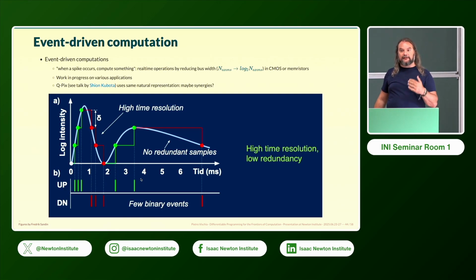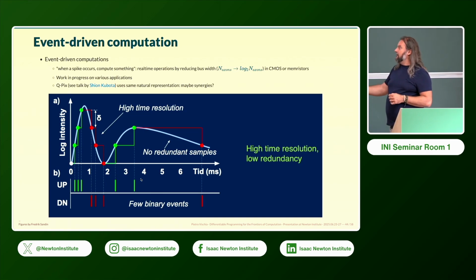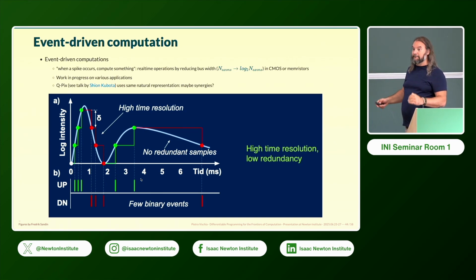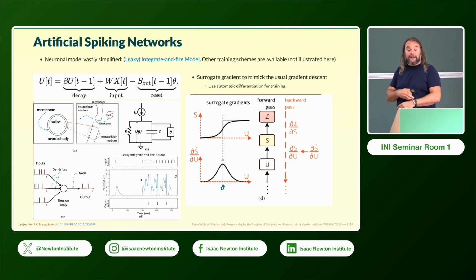Because the largest energy cost, and therefore also money cost, in chips is when you have to read out something from the memory. So if you have some weights encoded in the memory and you have to read them, that's bad. With matrix multiplication, you always have to read things, even if the matrix is sparse or mostly zero, you have to read the zero and multiply. With this paradigm, you don't do anything if the problem is sparse. And therefore, you get a massive improvement in energy consumption.